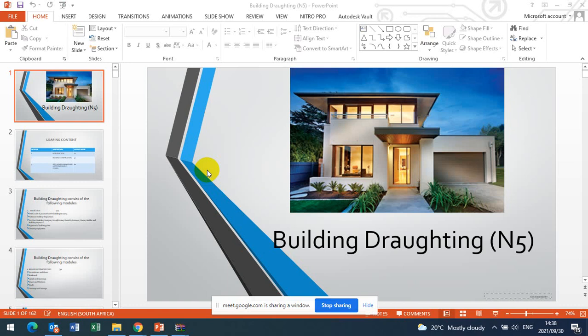Question 2 in the exam question paper is the floor plan. A floor plan is a sectional floor plan, we call it, because we are looking from the top of the house, and then we have to show what is in the house, all the room partitions and all the brick thicknesses, everything. We cut halfway through the window or along the house all the way and remove the roof. And then we are viewing from the top. We call it a floor plan. It's a detailed floor plan.